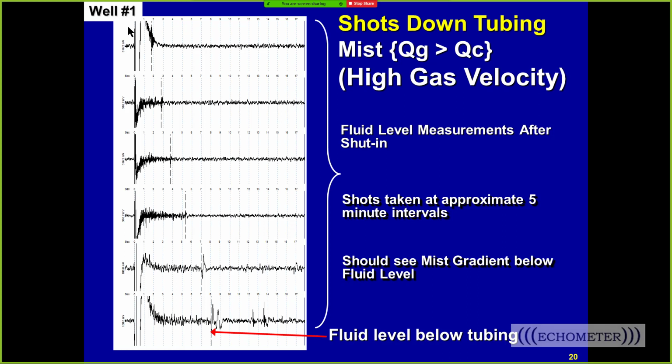Yeah. So the conclusion is, if you get all these shots that there's no liquid in the tubing, these wells are just bad wells. They're not liquid loaded, and so if you shut the well in and you hide the liquid that's in the tubing, then you're going to misanalyze the well.